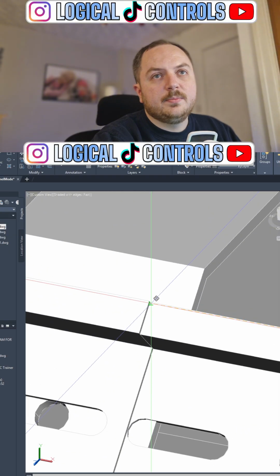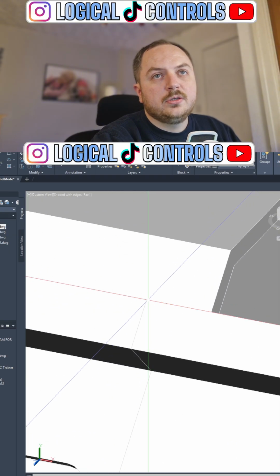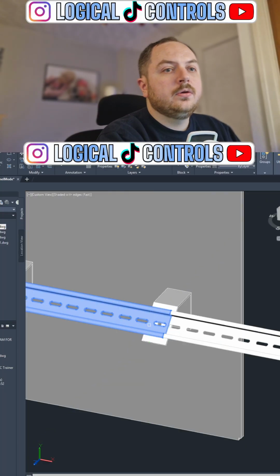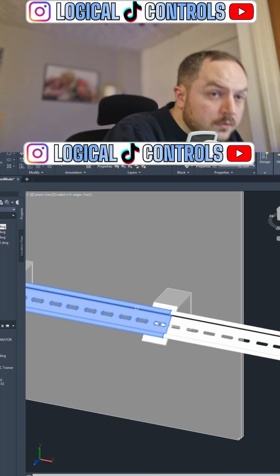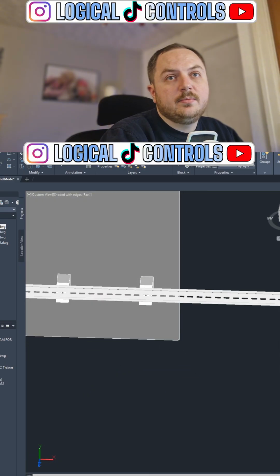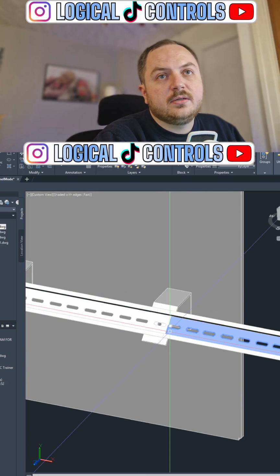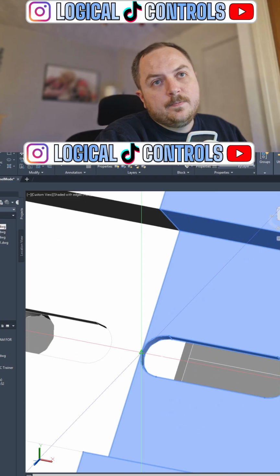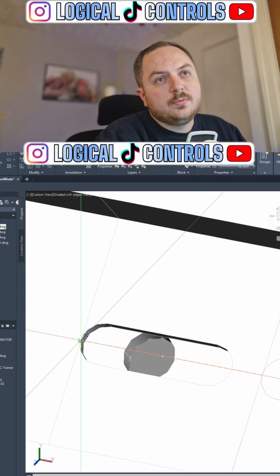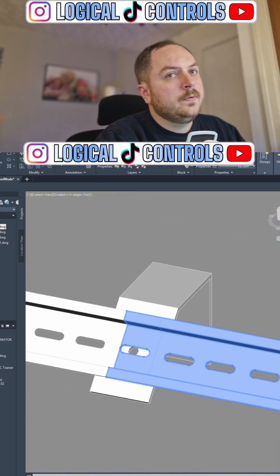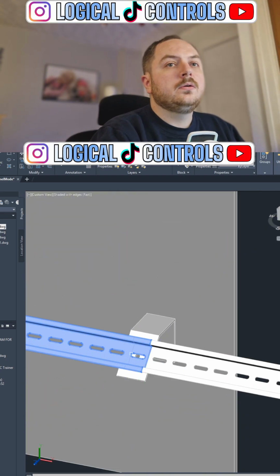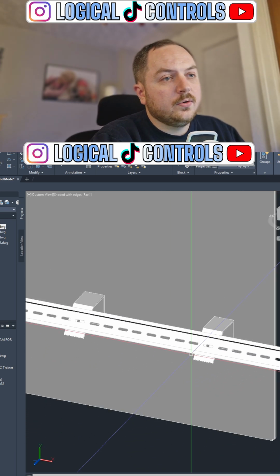So to make it longer, I'll just copy it across, join the two where I need them, and do a union to join them. Although, I joined them in a bad place because that wants to be over there. Union now. If anyone's not following, just let me know.